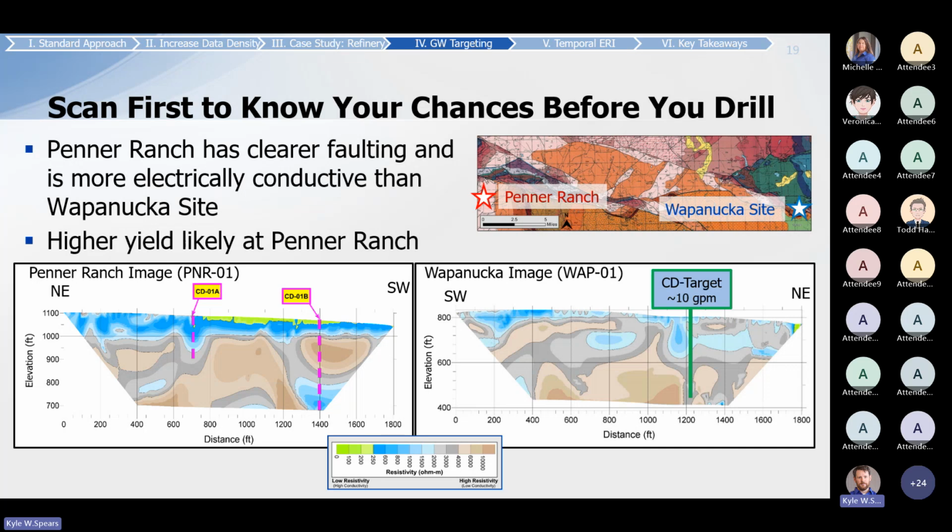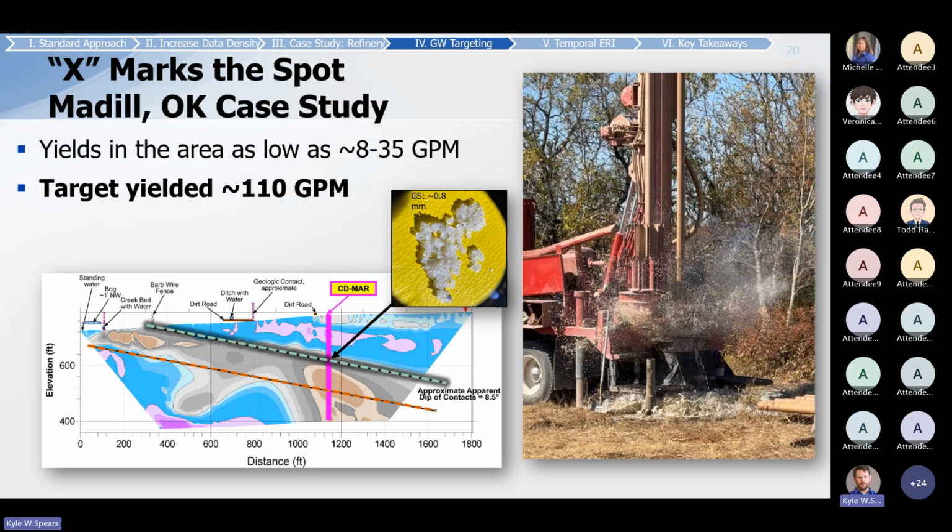Well, that's in a fractured carbonate aquifer. If we go over here to a sand aquifer, now we're looking at a sand aquifer that's overlain by shales and clay, and those are very conductive because of the mineral content. And so now we're looking for the resistive spots as being the ones to contain more water. So this interpretation process is nuanced, and it really does take that homework to get good targets for our clients.